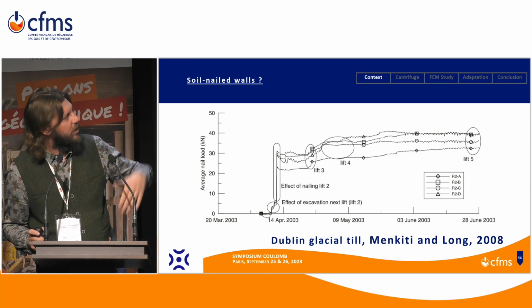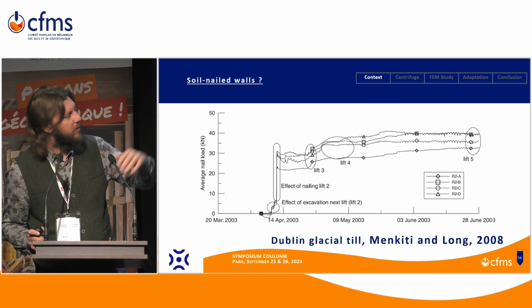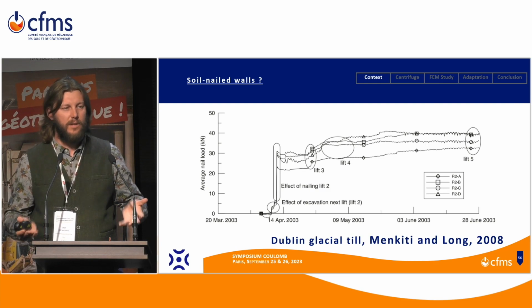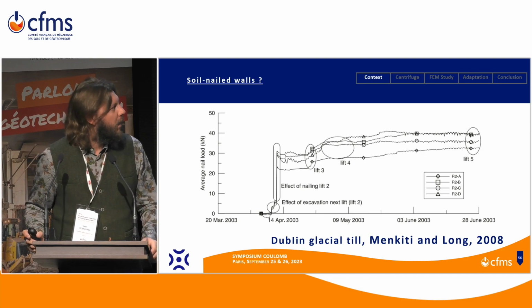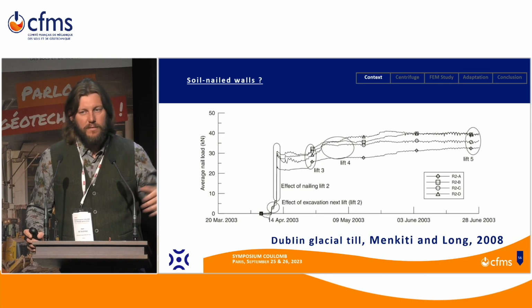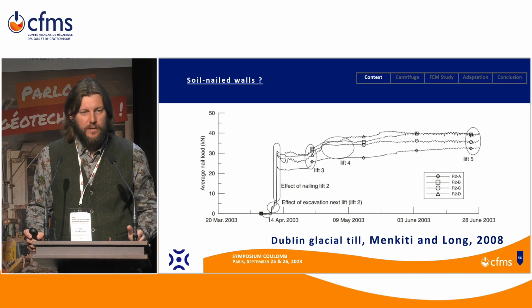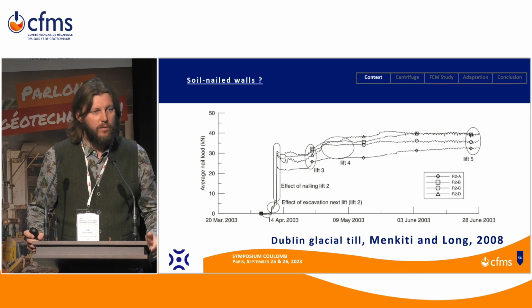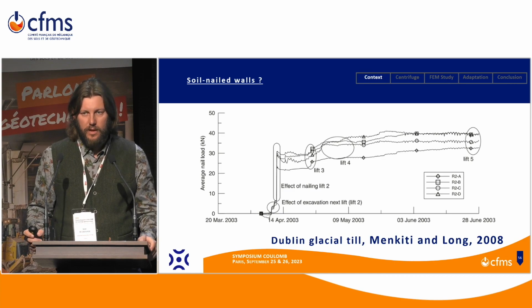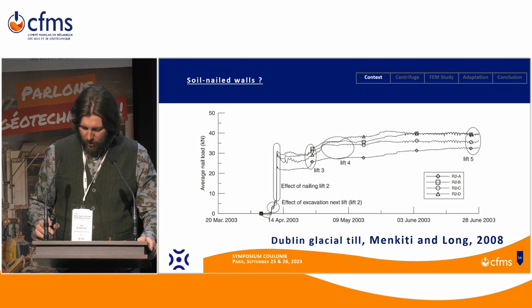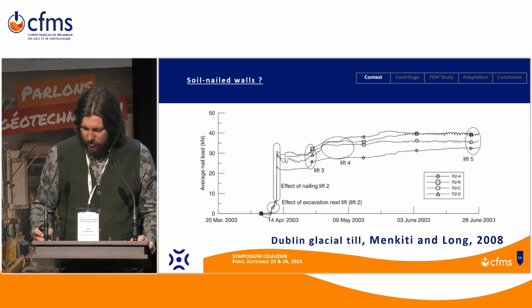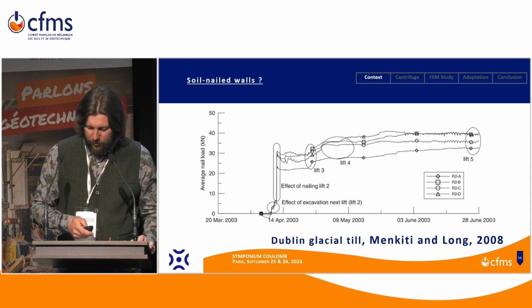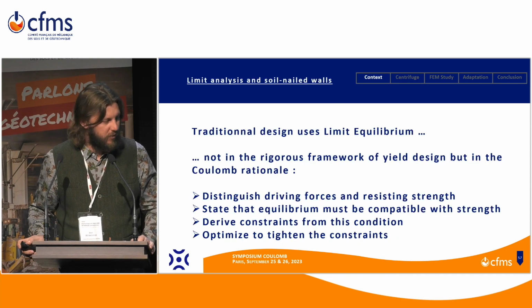The tension increases a lot. The third lift also increases the mobilization of the nail. And the 4th and 5th lift do almost nothing. So the phasing is really important in the mobilization of the nail. Okay, so it's just an example, but it illustrates quite well the idea.